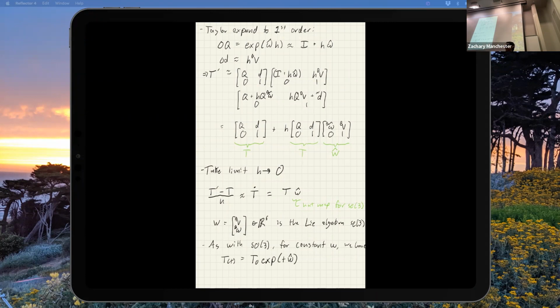Why is that? I don't know. So what if I flip the order? What happens? I get the wrong answer because matrices don't commute, right? But does anyone have any thoughts on what's going on there? What would be happening if I flip the order? Yeah, opposite direction, yeah. So here's a way to think about this. This guy's in the body frame, and this is body to inertial. What happens if I flip the order and I put the W hat on the other side?